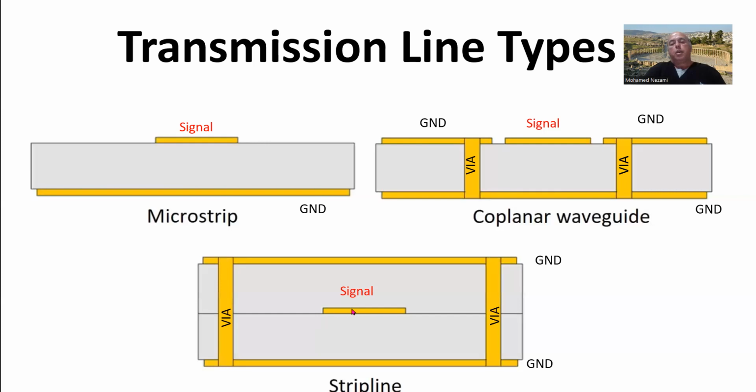A strip line is nothing but the same as a microstrip line, okay, but sandwiched between two ground layers, one on top, one on the bottom. And you can see, this one is exposed to the ambient, where this one is not, is bounded. This one is exposed, this one is not. This is inside. So a lot of times when you're doing a jumper, meaning you have to jump over another